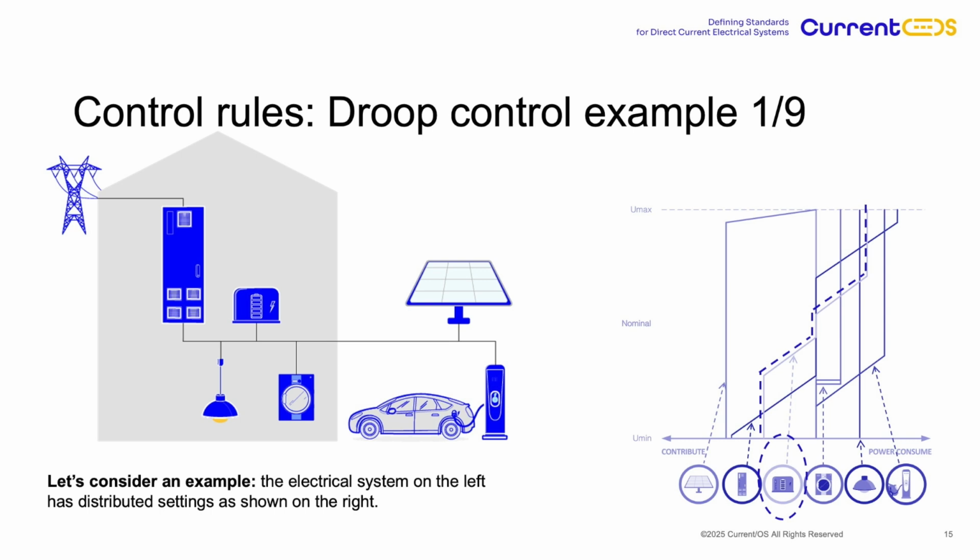In this example, the battery is programmed to contribute before importing from the grid and to discharge fully before exporting power to the public grid. This setup supports an energy self-consumption strategy, although it can be adjusted for other priorities. Now let's look at the loads.